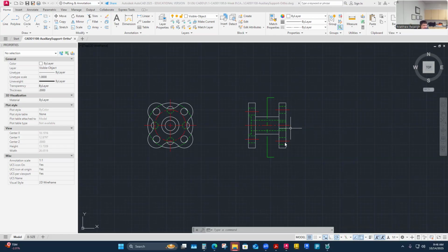And really, I probably wouldn't even have to do the viewing plane now that I think about it, because if it's just a back view, I just keep them in orthographic alignment and say that's front, that's back. Maybe it's helpful to title my views when I do that. And if I don't title my views, it might be helpful to actually put the viewing plane arrows in, call it a viewing plane, and title that view.